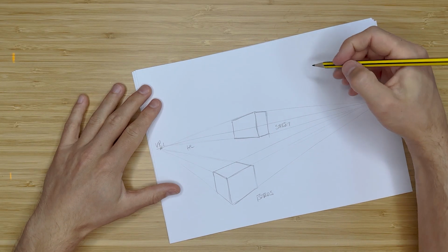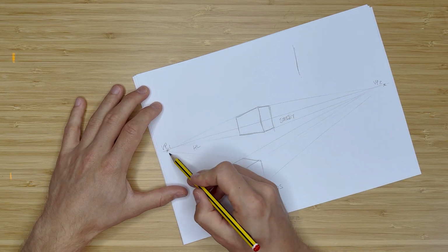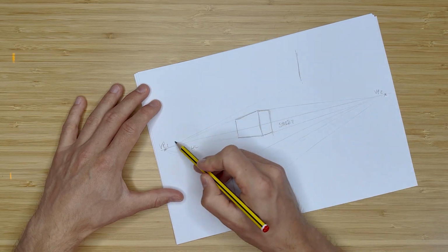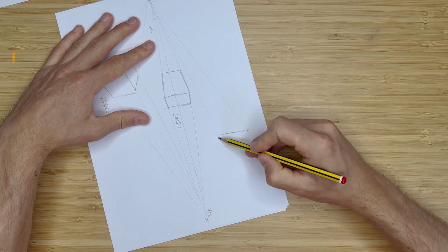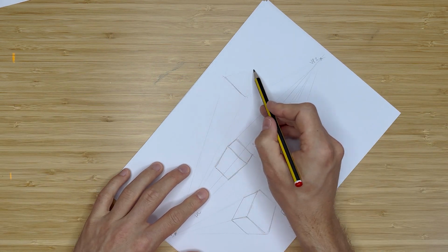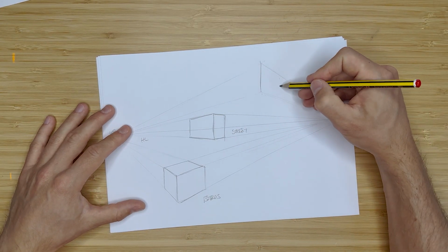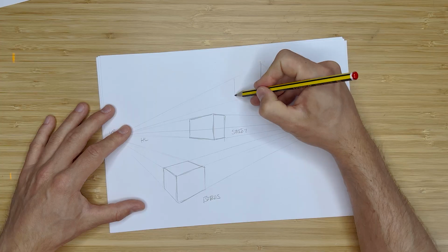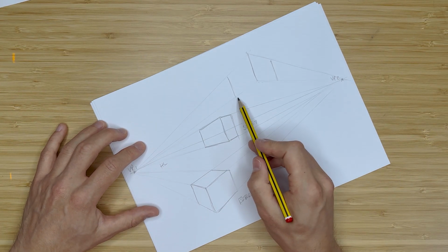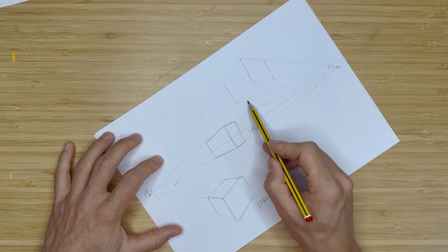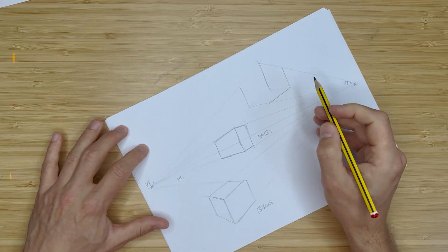And then we're going to choose a worm's eye view here. So we're going to get a single line like so. Hope you understand by now. From the bottom, we're going to go to this vanishing point. From the top to this vanishing point. Same on this side. From this vanishing point to here. And from this vanishing point to the top of our line. So we've got a vertical, vanishing points are sorted. We now need to get our vertical line for this one, which is going vertical here and across there. And then because we can see the bottom part of the cube, so we're looking up at it, from this point, we're going to go to this vanishing point over here, and from this one to this vanishing point. And then we can draw over our cuboid,